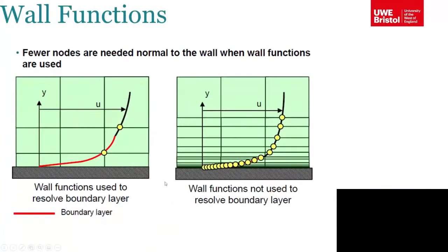So this is what it is if you use a lot of grid nodes and solve it. Then what you do is you get the shape of that, write an equation for the shape, and then not use many grid nodes, and apply that shape to the near wall region. You will get the same result, kind of.